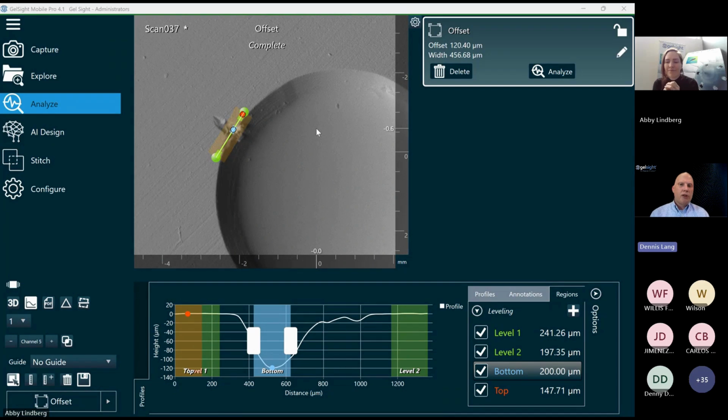And when an aircraft comes in, even a new aircraft, actually, if it has a pitot tube mounted, you don't want to remove these, and certainly in MRO, they're not typically removed. But a pitot tube has a chamfered end like this, and if it's been flying, of course, it's sustaining damage from various kinds of debris that are in the air, so airborne particulates, bugs, different things are hitting it. Potentially some, a handler accidentally hits it. But in addition to that, there's just the manufacturing tolerances that are there.